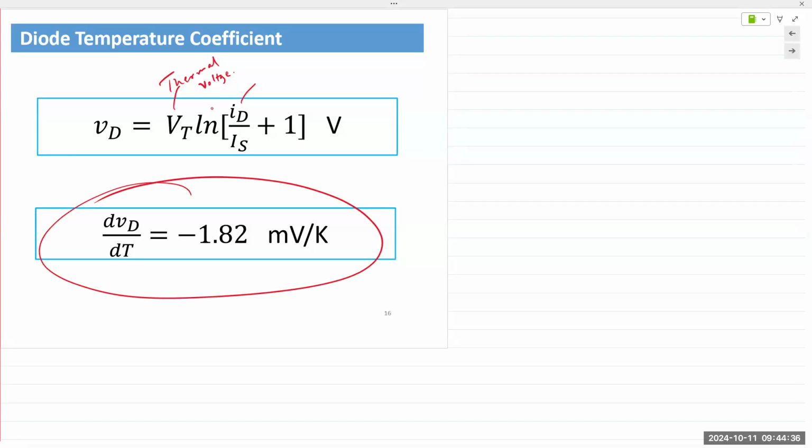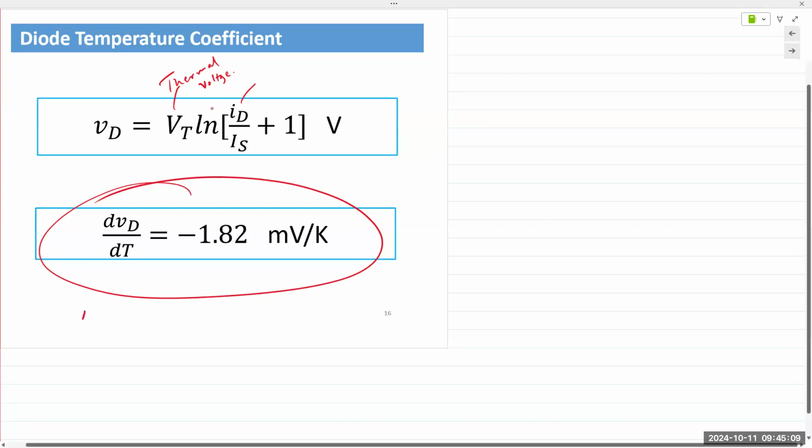And that was what procedure 3 in the lab was. Procedures 1 and 2 are in the lab manual, and 3 was the procedure I wrote out in the lab notebook, and that had to do with simulating the diode voltage as a function of temperature. So you could increase it for one, and if you plotted the graph, you could see that the diode voltage decreased linearly as a function of increasing temperature. And it finds application, and I really like this example, it's in the book, it finds application in digital thermometers.